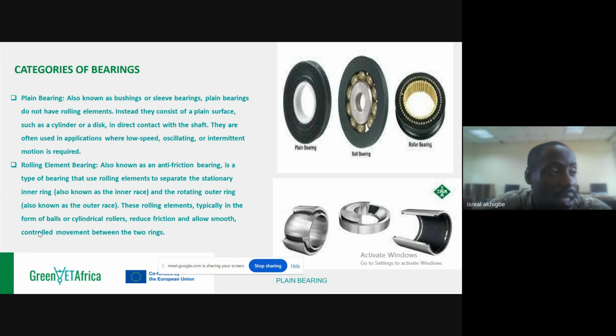Yes, so now this is the thing. Usually when manufacturers make chains, the video I played, the centers, the pitch, that video was showing using a vernier caliper to measure the pitches, to measure the side plates, etc. The manufacturer already has a specified rating for those chains. So it's best when you are going to replace a chain, you take that same chain or you measure those parameters: the chain centers, the pitches, the thickness, and the pin or the roller. Then go to where you purchase your chain and get that equivalent.